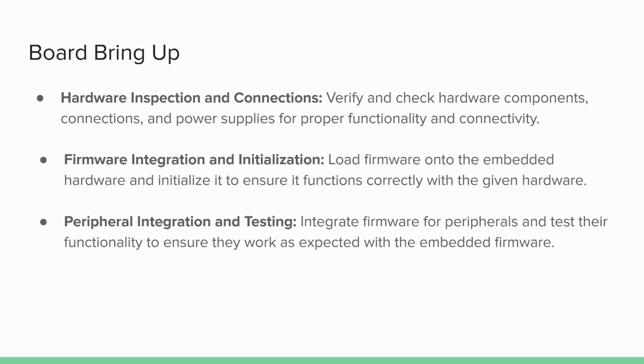Next, we need to work on the peripheral integration and testing part as well. For example, you have tested one chip. In most projects you are going to have multiple chips on a single board. So you have to have functions for each peripheral so that you can talk to them individually, making sure you are able to say yes, all peripherals are responding. Maybe you can print on the debug console how many peripherals you have and whether all of them are responding.